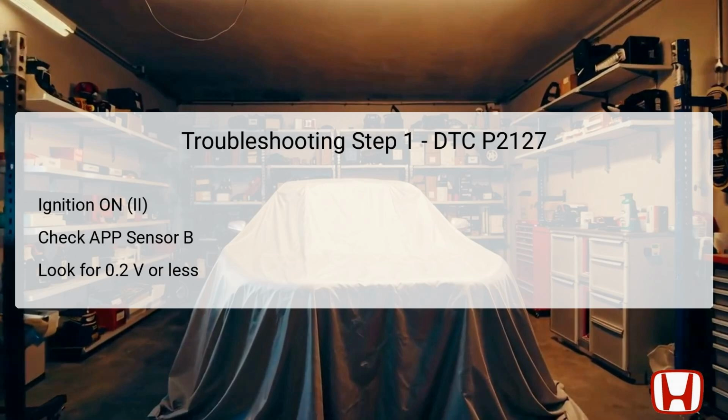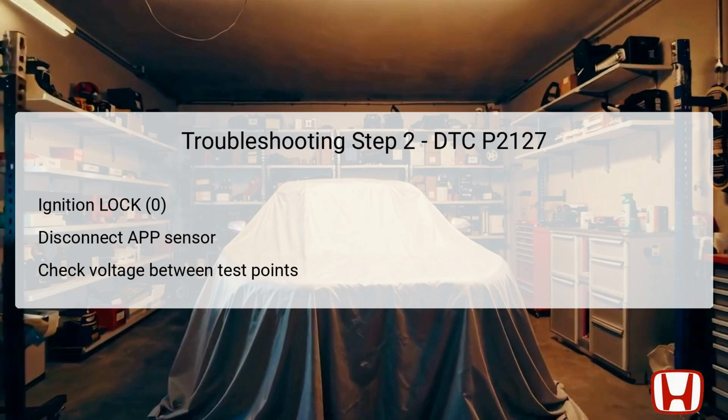Step 2 requires turning the ignition switch to the LOCK 0 position and then disconnecting the APP sensor 6P connector. Once this is done, turn the ignition back to ON. Measure the voltage between two specified test points, specifically between test points number 2, LT blue, and number 3, gray, at the APP sensor connector. This test checks the VCC5 line.